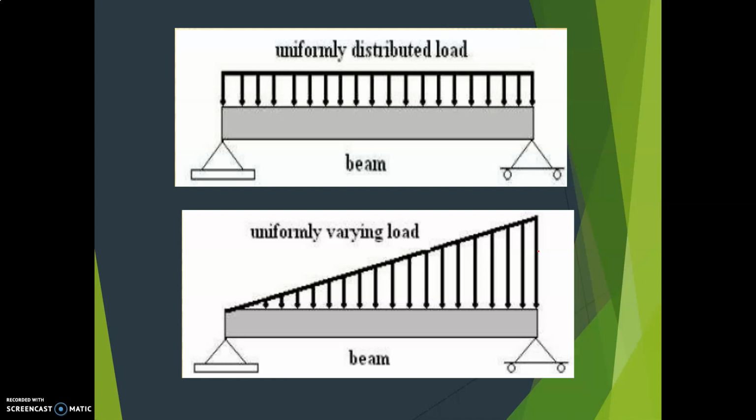And again here also you have to convert it into an equivalent concentrated load. That means you have to convert it into a load. How can you convert it into a load? Half into base into height. That load is equal to the area of the triangle.